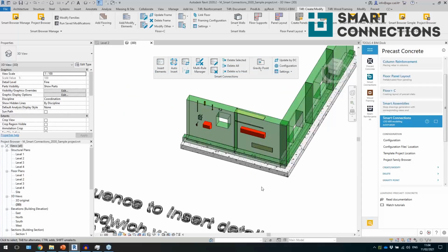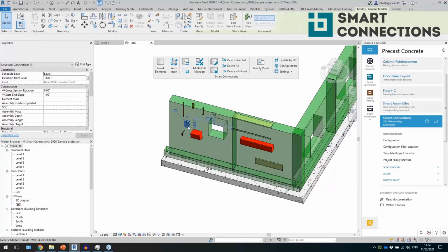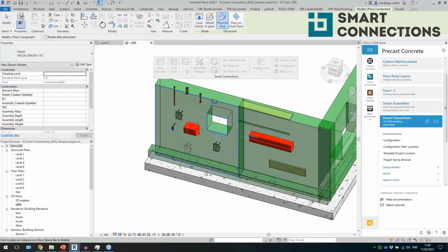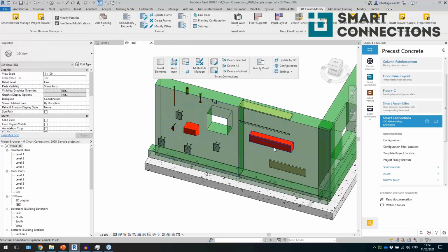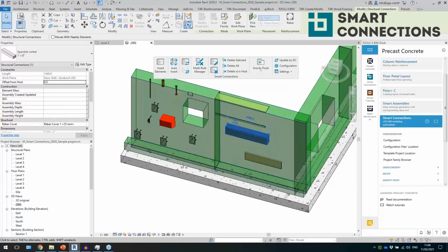A little bit about the families which you can use with this tool. As I said, these are point-based families. A point-based family means that I click once and it's inserted. That's how I do it with Revit: I just pick the face where I want to place it, and I can drop it. A line-based family is when you need to click twice.